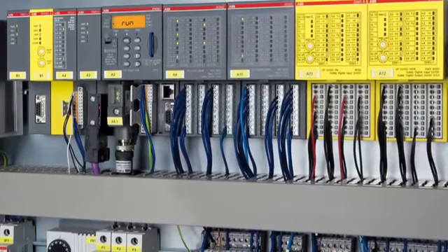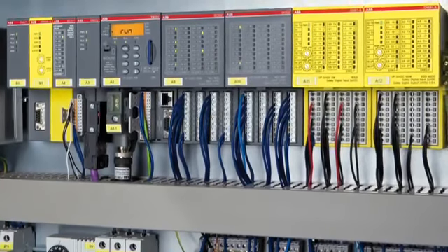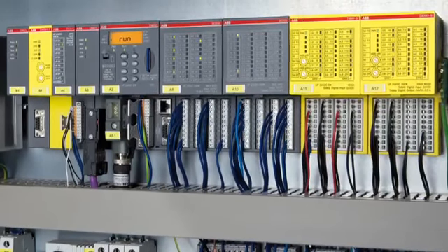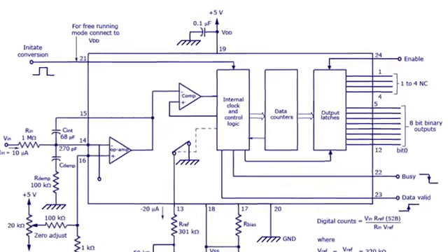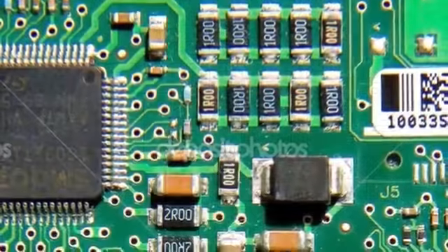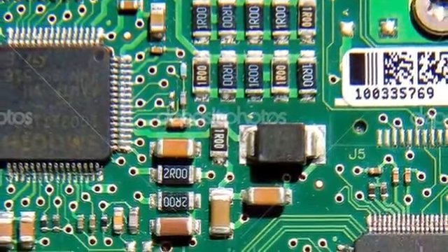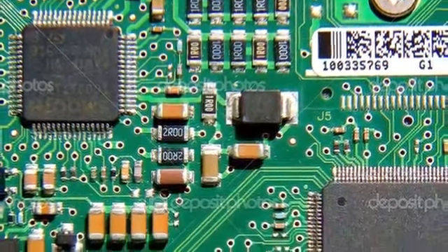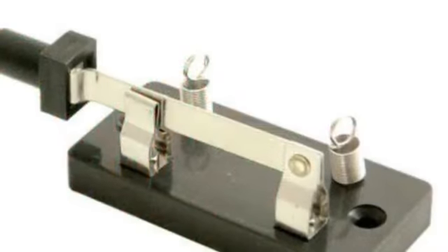The PLC must now determine if the analog signal reveals a dangerous condition by comparing the level of the analog signal with pre-programmed set points. Here is what actually occurs. The retransmitted analog 4 to 20 milliamp signal must be converted back to the digital domain for processing inside the safety PLC's electronics. The level of the signal is compared to a pre-programmed threshold that is set at the limit of safe operation. If the signal level is determined to be within the safe limits of operation, a relay inside the safety PLC will remain closed.